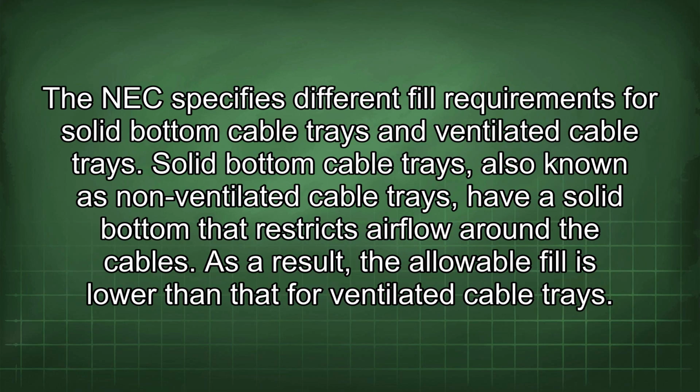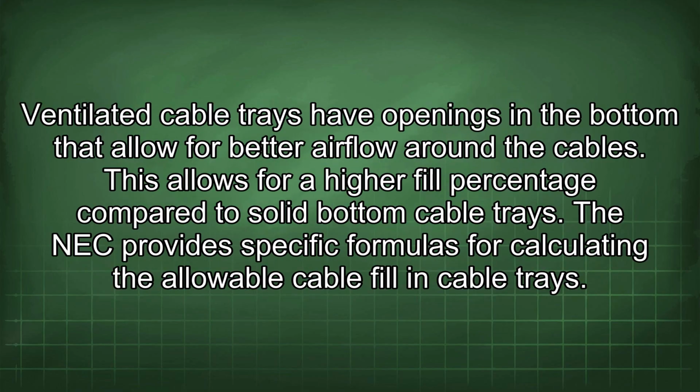The NEC specifies different fill requirements for solid bottom cable trays and ventilated cable trays. Solid bottom cable trays, also known as non-ventilated cable trays, have a solid bottom that restricts airflow around the cables. As a result, the allowable fill is lower than that for ventilated cable trays. Ventilated cable trays have openings in the bottom that allow for better airflow around the cables. This allows for a higher fill percentage compared to solid bottom cable trays.